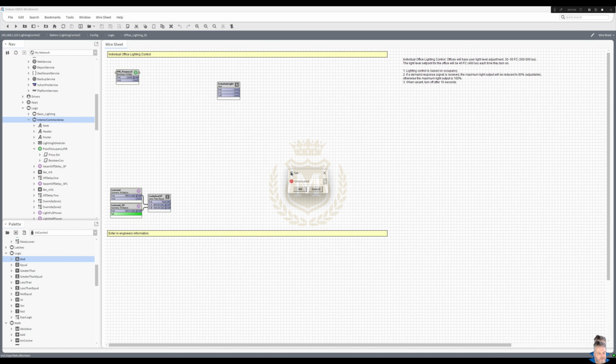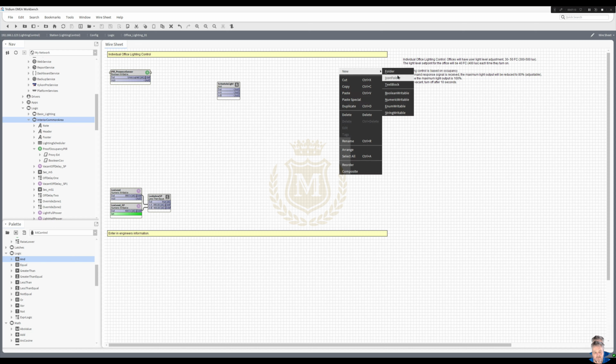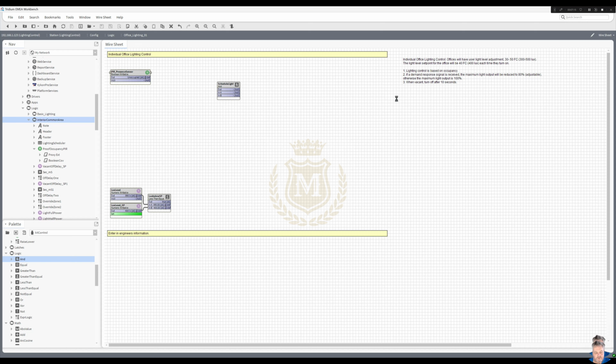Actions, set that to unoccupied for now. But we're going to composite that to the outside eventually. Presume we need a light, so let's just do a light. It's going to be numeric because it's DALI and it uses 0 to 100%. So we'd put in light output.